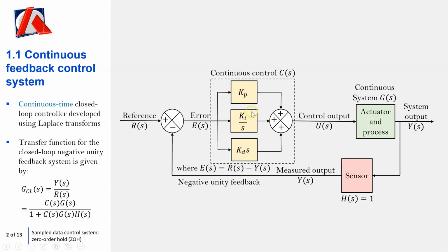So you're looking at effectively the area of the error, the rate of change in the error, and then just having this multiplier. And effectively what you do is you tune these Kp, Ki, Kd to give them values for a certain application depending on what your system is, and if it's well tuned, it'll perform as you expect, and it'll compensate for things such as disturbances, maybe wear and tear on the system. So these three terms combined are very, very powerful for getting a system to behave in a desired manner. Okay, so your reference is what you desire, system output is what you actually get, and what you're doing is effectively configuring the continuous controller, in this case, to give you that desired performance.